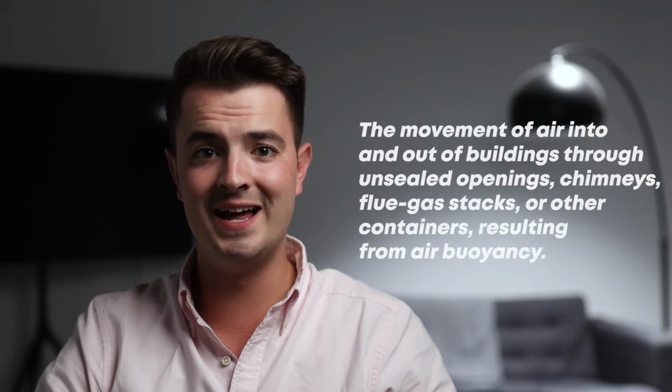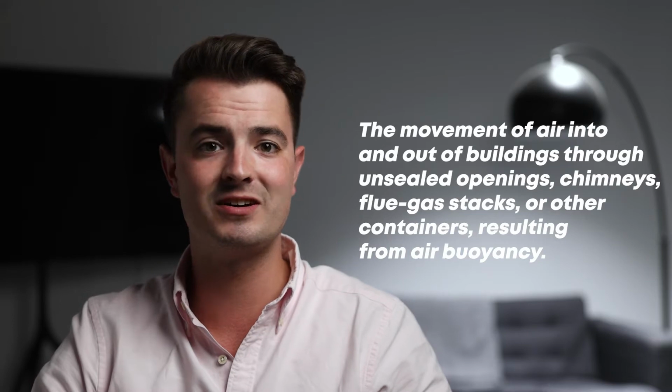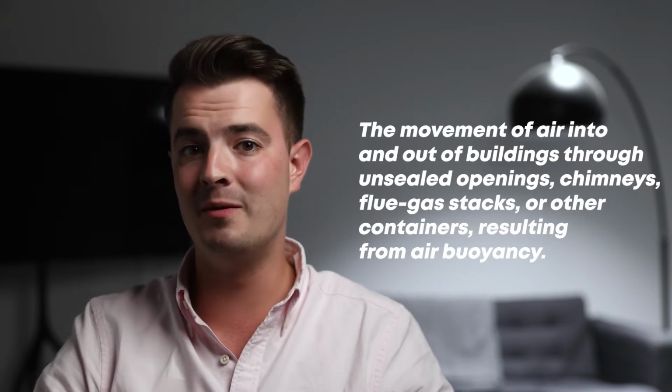The stack effect, sometimes known as the chimney effect, is the movement of air into and out of buildings through unsealed openings, chimneys, flue gas stacks, or other containers, resulting from air buoyancy. Buoyancy occurs due to a difference in indoor to outdoor air density resulting from temperature and moisture differences. The result is either a positive or negative buoyancy force. The greater the thermal difference and height of the structure, the greater the buoyancy force, and thus we have the stack effect. The stack effect helps drive natural ventilation, air infiltration, and unfortunately, fires.